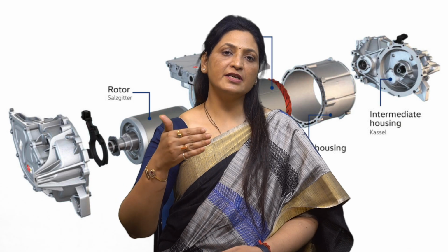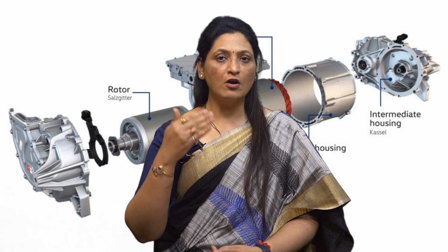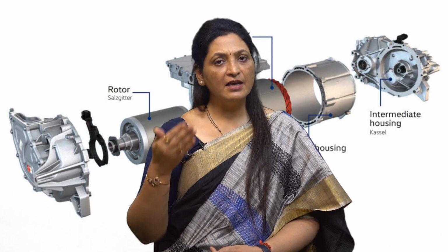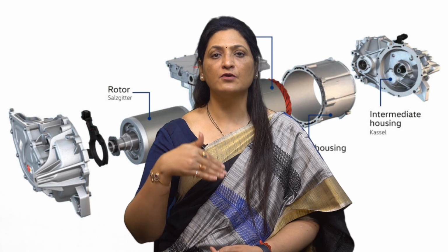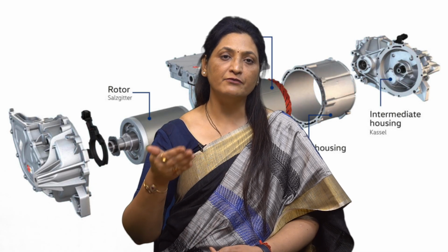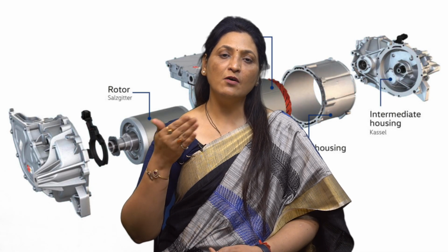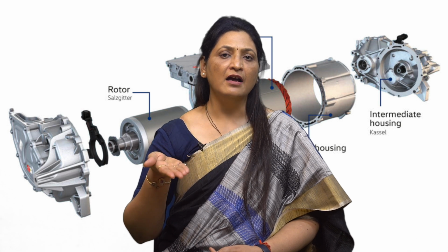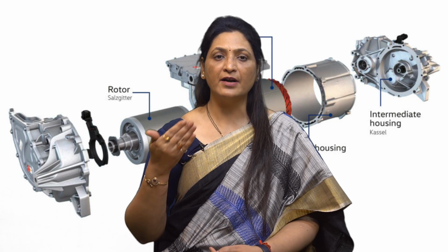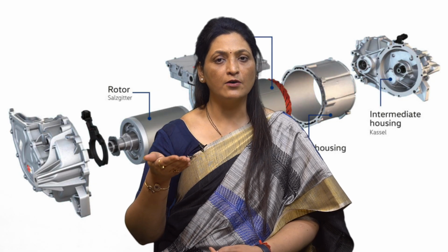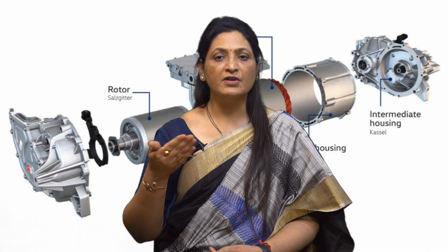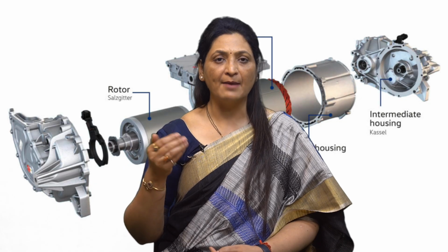The last component is the electrical source. Electrical sources or power supplies provide the energy to the electrical motors. For high efficiency operation, the power obtained from the electrical sources needs to be regulated using the power electronic converters. The power sources can be of AC or DC in nature and are normally uncontrollable, that is, their magnitudes or frequencies are fixed or depend on the sources of energy such as solar or wind. AC source can be either 3-phase or single phase. 3-phase sources are normally for higher power applications.